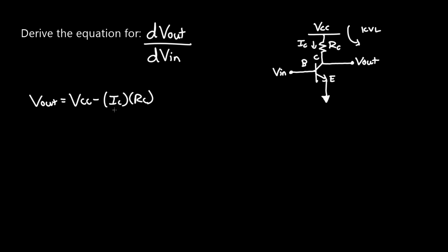is the collector current. Now that we have that established, we need to change some variables around, because of course, it can't be that easy. So, we also need to understand that we have a couple other formulas where IC equals saturation current IS E to the VBE over VT, where VBE is the potential difference between the base up here and the emitter down here. And VT is thermal voltage, which is 26 millivolts roughly, so you don't have to worry about where we're getting that from. But this is a small signal analysis formula that you'll see throughout the entire analog course anyways, so get used to it now.